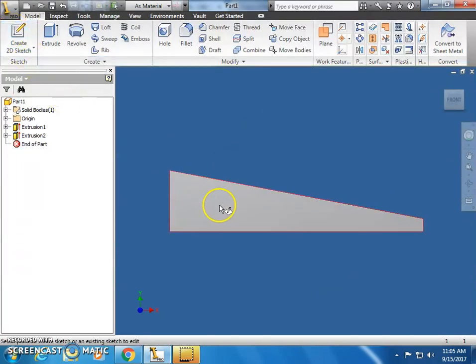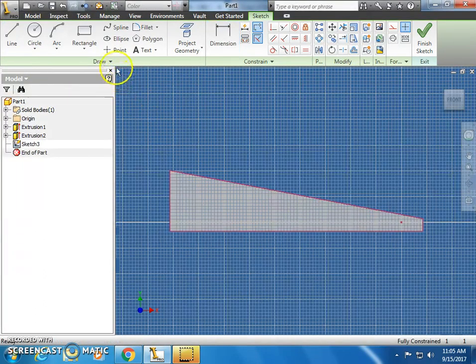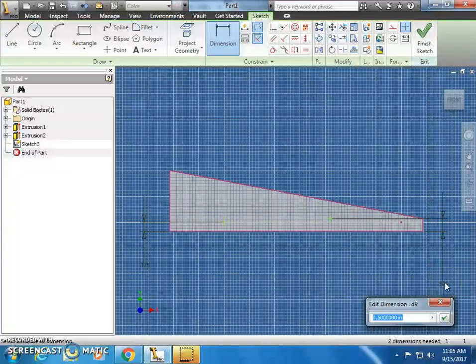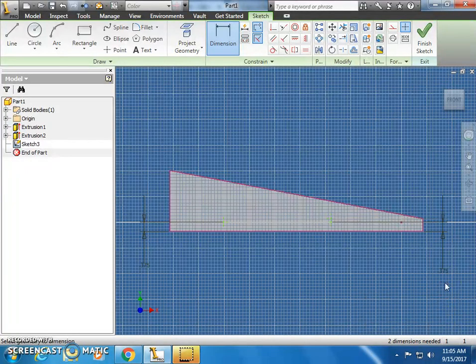Again, you want to sketch on that surface, and you're going to use the point tool. You can click anywhere to begin with, and then when you click on Dimension, your wheels need to touch the ground. So click where your axle is going to be, click on the bottom part of the dragster, and bring it over. This needs to be 0.375. If it is not 0.375, your wheels will not touch the ground, and your dragster will not go anywhere. So please click on the axle and the bottom of the car, bring it out and make it 0.375.